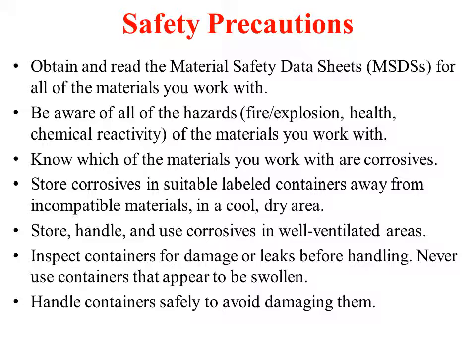Incompatible materials are such materials which may cause fire or explosion or some chemical reaction with the chemicals that are already stored in the containers. So the incompatible materials should be properly separated. And of course, the corrosive container should be stored in a cool and dry area.